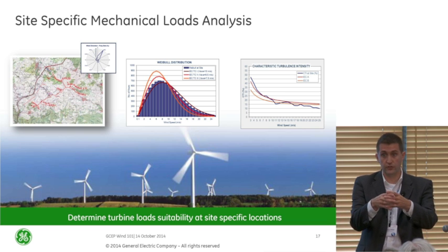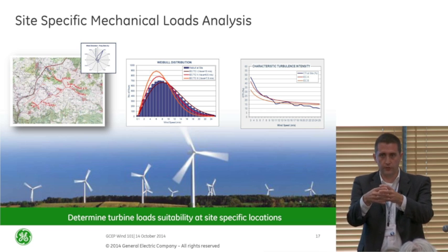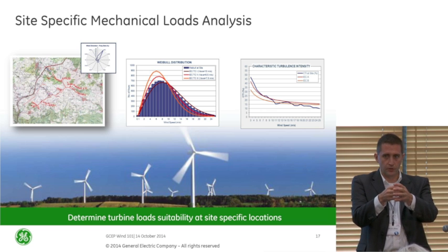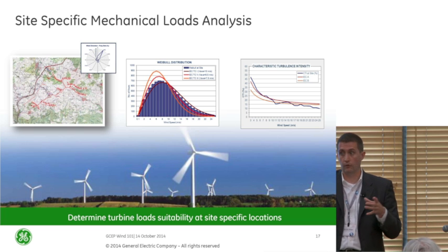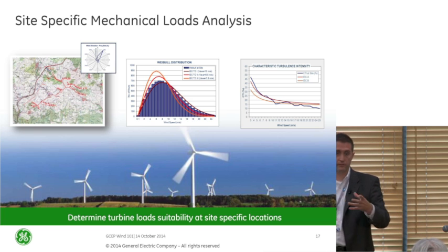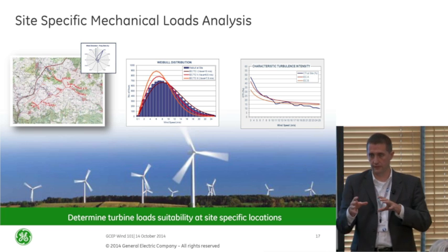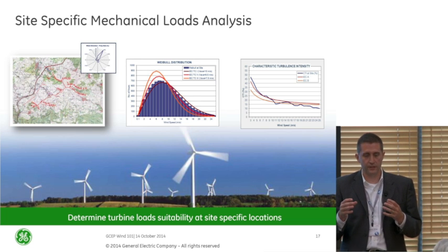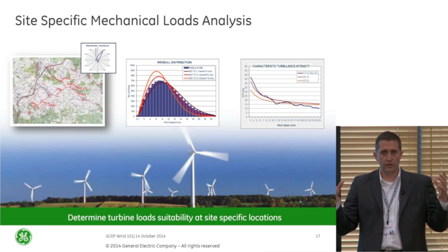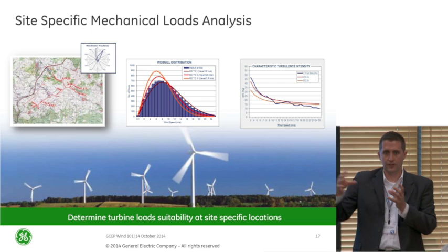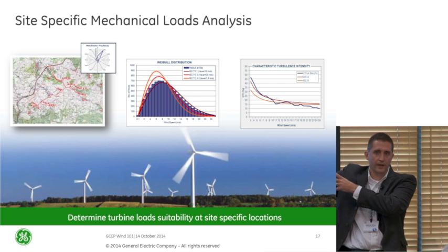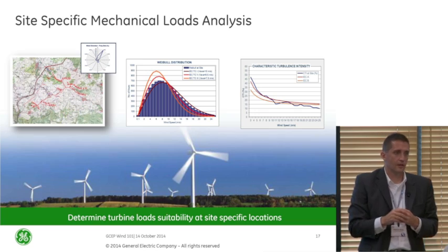And sometimes the answer is no, and you need to either get rid of that turbine, or maybe you need to move that turbine to a slightly different location in the farm. So there is some movement around in terms of, okay, this is a very turbulent area. And in fact, going back to where I talked about the wind direction changing, I'm trying to site a turbine and I'm getting all this turbulence in it, and it's a little bit more laminar if I move it over this way. So it's going to be more important for me to do that. So this is a way for them to do it.